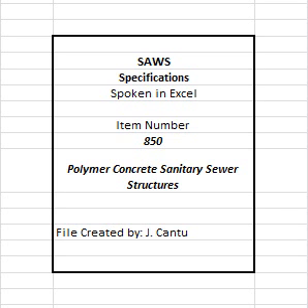All aggregate, sand, and quartz powder shall meet the requirements of ASTM C33, where applicable. B. No Portland cement shall be allowed as part of the mix design matrix. C. All sand and aggregate shall be inert in an acidic environment. 8. Reinforcement shall use steel reinforcement or acid-resistant reinforcement, FRP bar in accordance with ACI 440.1R, for polymer concrete design.